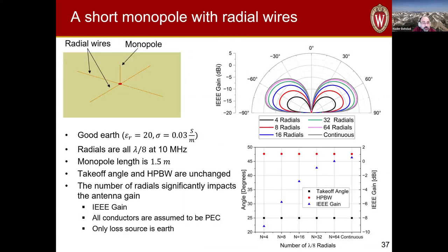So what would be more practical is to implement our ground plane not necessarily with a continuous ground plane, but rather with a bunch of radial lines here.